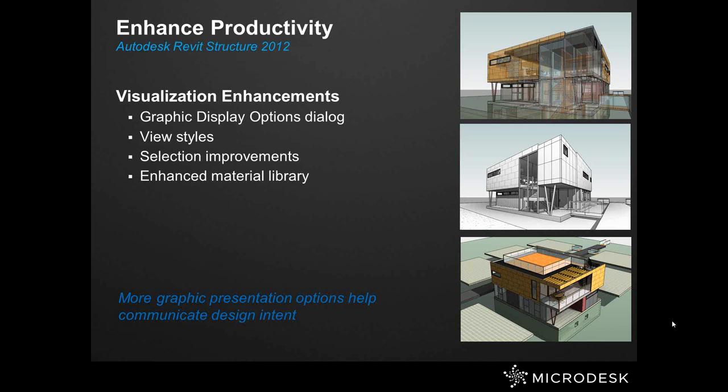You have the ability to manage your material property sets by using the Material Properties Library dialog. You can modify a set, load a property set from a library, or delete all unused property sets and materials from a project. You can now browse for a materials library that has been previously created. It extends your rendering capabilities because you can share different property sets from different rendering software. You can also remove a library that you no longer need to keep your project organized.